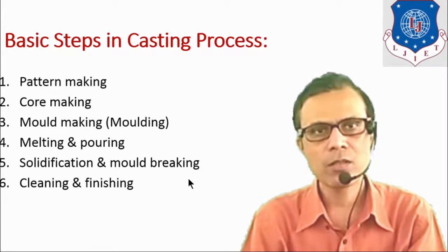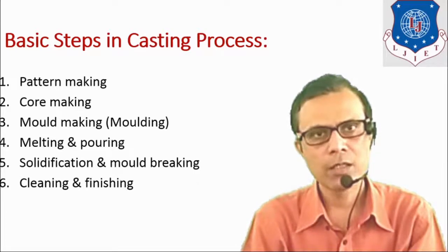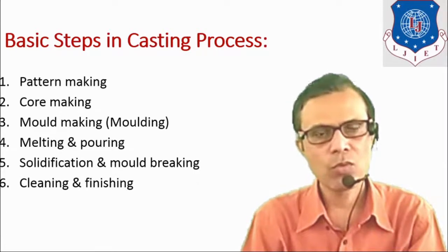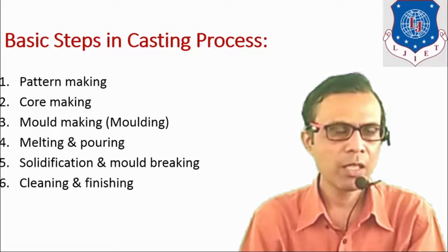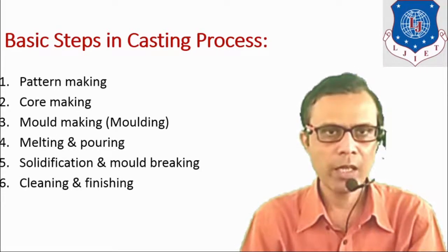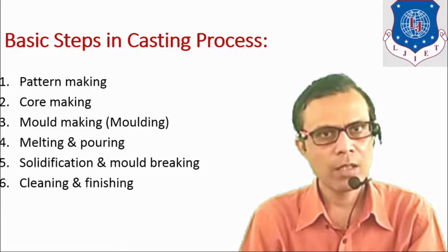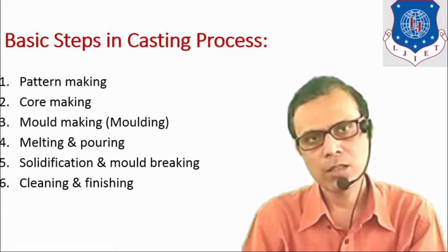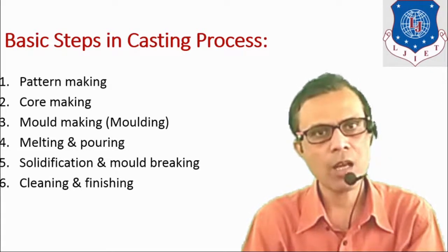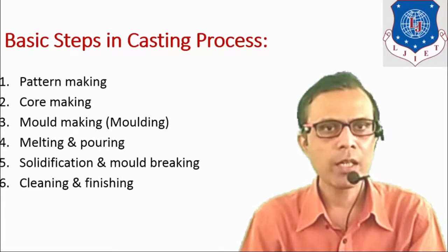Then solidification and mold breaking. After completion of metal pouring, it is allowed to cool down or solidify for some time. Then the mold is broken and the solidified piece is taken out, which is actually the required casting.